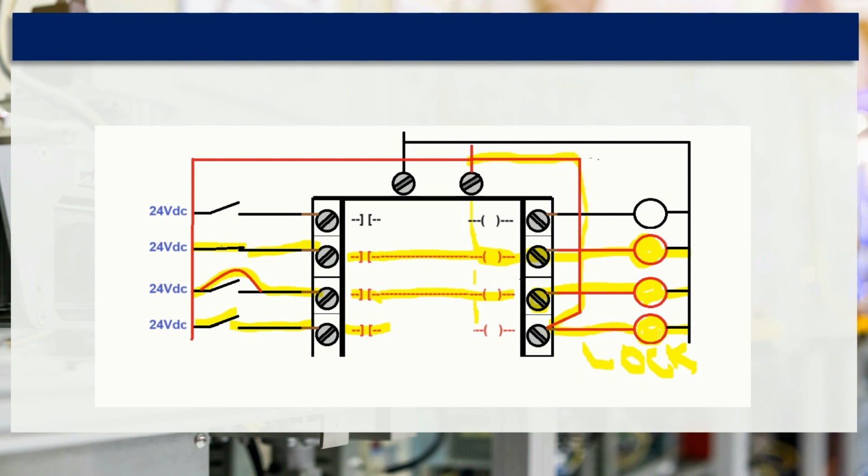Now it's behaving properly. So it's really important when you're working with forcing to understand the difference between the inputs and the outputs, and the fact that you can't do internals, you can only do the real physical world. Once you force on an input, it's resolved in the logic. When you force on an output, it is not resolved in the logic. It's like literally running the jumper wire on the outside to bypass the PLC. The PLC will not resolve it in logic.